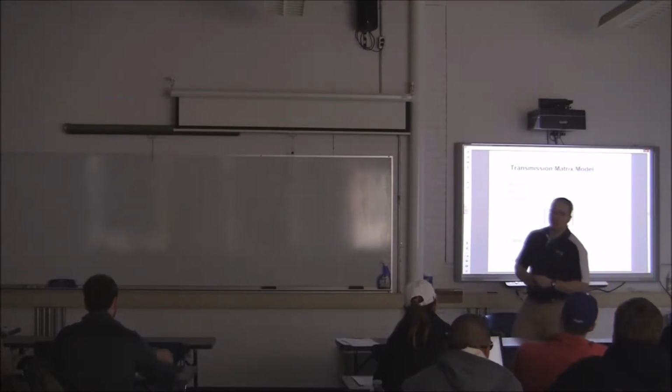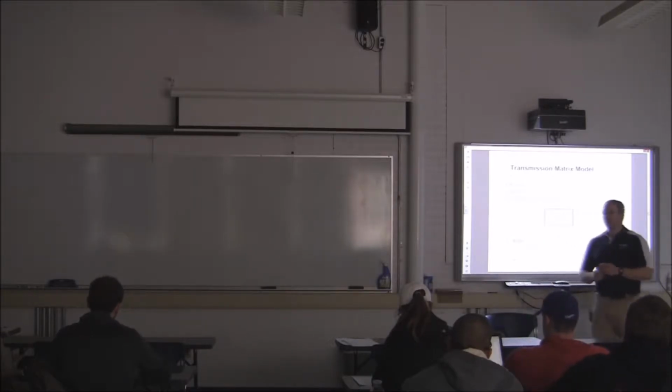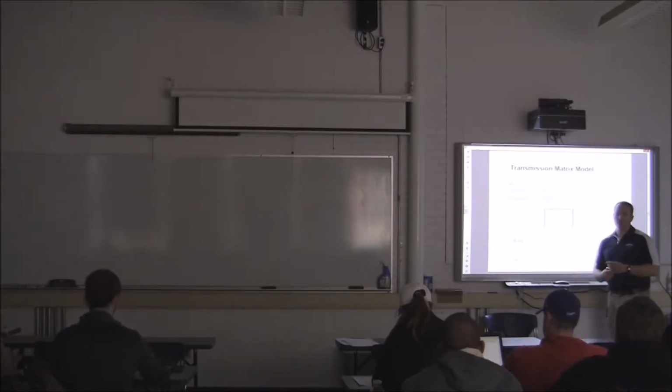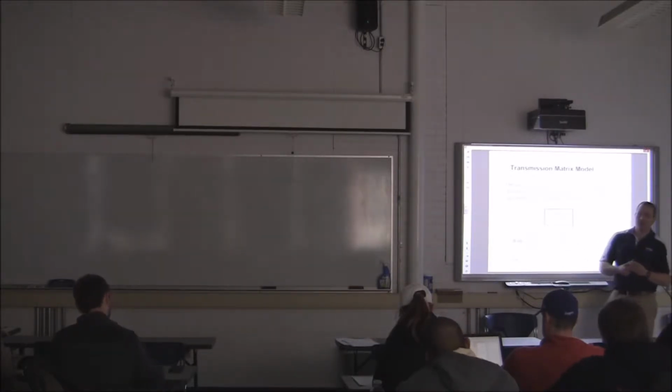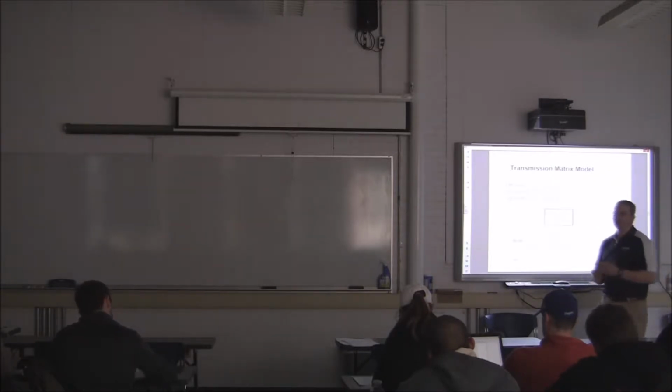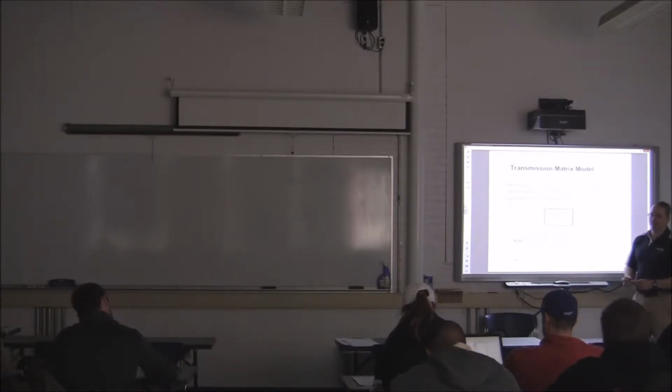If 1 over ohms is a mho, so this is just units of mhos. And then amps equals D times amps. What does D need to be? Unitless quantity. So this is a hybrid two-port approach because it has a mix of different units. Okay?